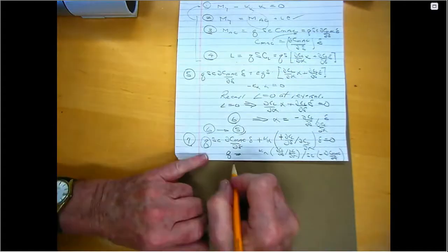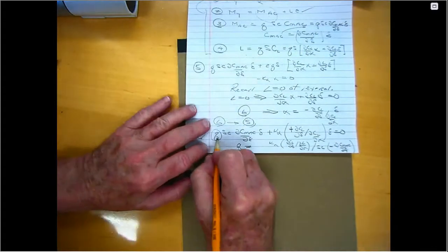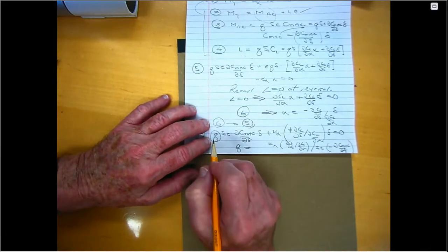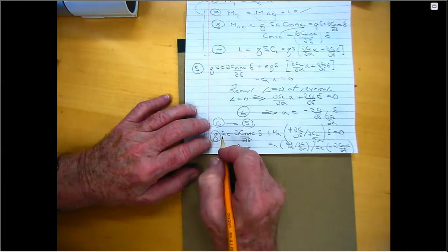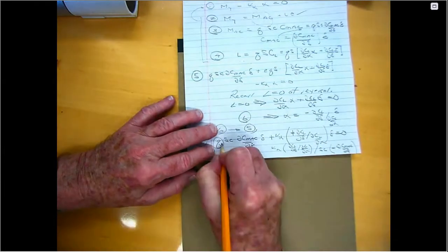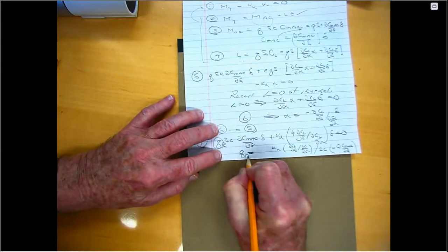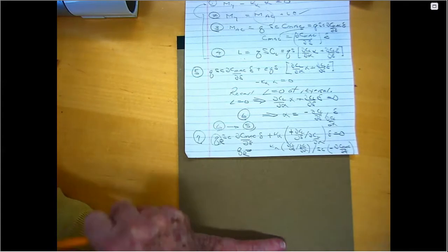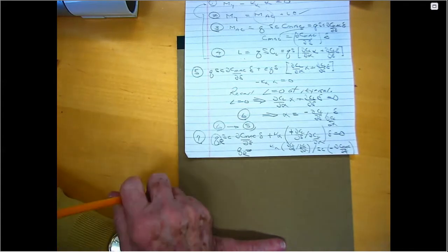So now what have I computed? Well, this is not just any old Q. This is a very special Q. This is the Q that makes the lift 0, because that's the way I assumed at the beginning of this exercise, right? So now I'm going to put an R here for reversal. This is the dynamic pressure at which reversal occurs. If I'm less than this dynamic pressure, the lift is positive.